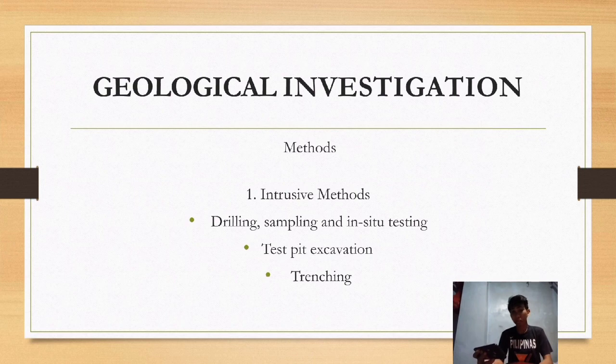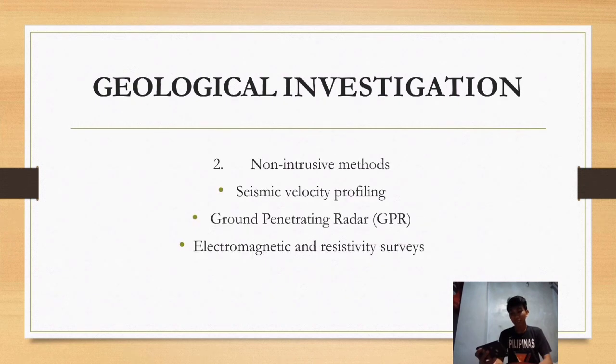There are two types of methods: intrusive methods and non-intrusive methods. Intrusive methods consist of drilling, sampling, and in situ testing, test pit excavation, and trenching. Non-intrusive methods consist of seismic velocity profiling, ground penetrating radar, known as GPR, and electromagnetic resistivity surveys.